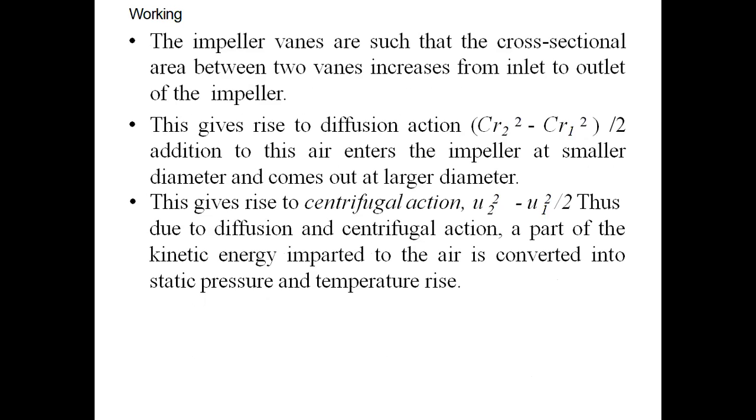The impeller vanes are such that the cross-sectional area between two vanes increases from inlet to outlet of the impeller. This gives rise to diffusion action, (Cr2 square minus Cr1 square) by 2. In addition to this, air enters the impeller at a smaller diameter and comes out at a larger diameter.